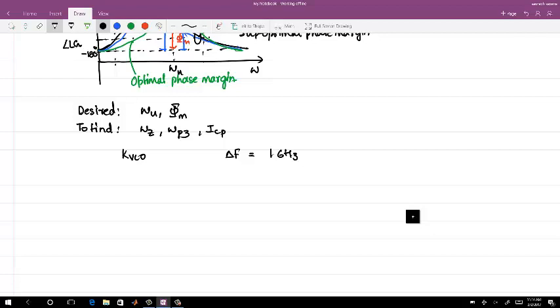I am talking of a very extreme case, that I can have a delta V control maximum of 1 volt, right? So ideally what I want from my VCO, if I change by 1 volt, this all depends on the control of the oscillator. Okay, so I should have a 1 gigahertz of change.